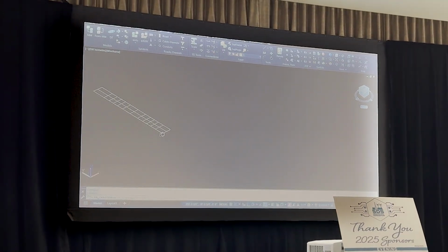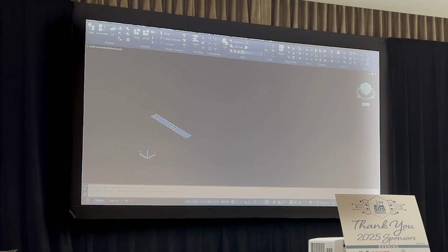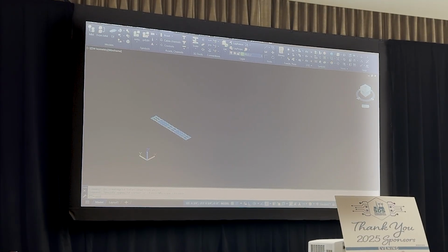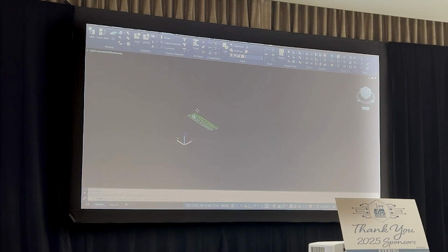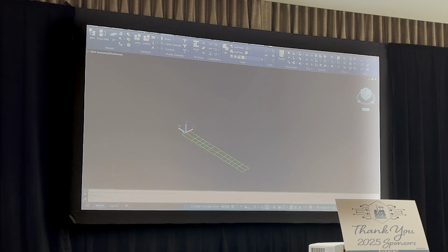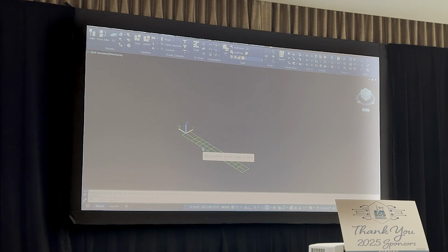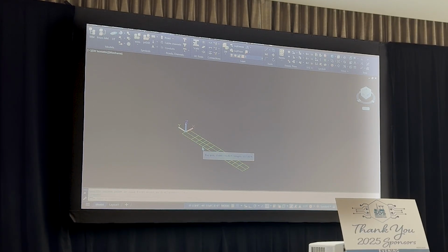It's going to make this grid, right? I'm going to snap this. In this case, I'm going to go ahead and move it. And I have something I want to be the center of my assembly. So I'm going to type move. I'm going to come over here because this is going to be where my transformer is. And I'm going to say that goes to 0, 0. And in this case, I want it pointing down that y-axis. And just like any other CAD software, that orientation, it's not overly important which direction it's facing, but it can make life easier if you know the direction it's supposed to be facing already.